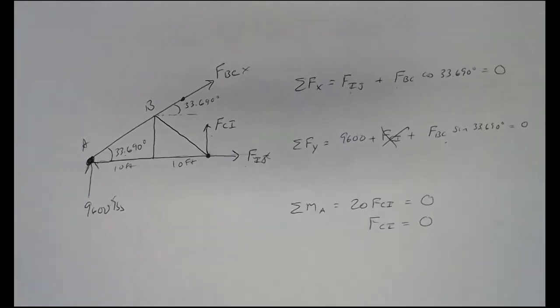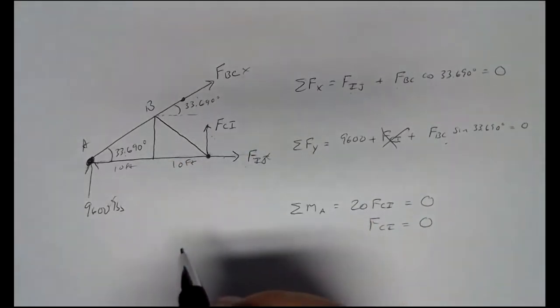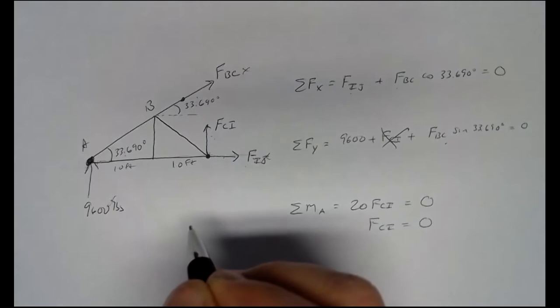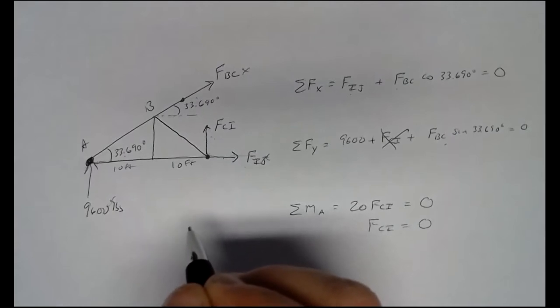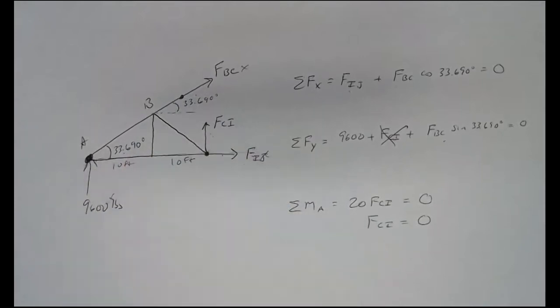Now, I'm not going to work through the rest of the algebra on that unless anyone really wants me to. But remember, interpretation of tension and compression is different in method of sections. In method of sections, by default, we assume everything is in tension, and if we get a negative result, it's in compression. So it's just easier to draw the free body diagram assuming tension. So that's the truss problem.